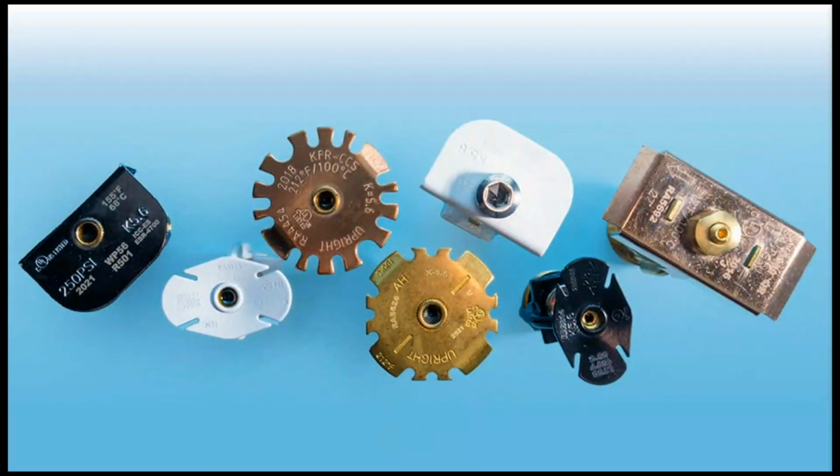Just to recap, we covered 8 types of special sprinklers. 2 of those sprinklers are just pure marketing. We have our MRI sprinkler and institutional sprinkler that fall into that category. But 6 of them were true NFPA special sprinklers that have special applications. Some that you're very familiar with, like windows and attics and concealed combustible. And then others that are new and unique, like corridor pendants, metal building sprinklers, in-rack storage sidewall sprinklers, and even anything else that might come up down the line.